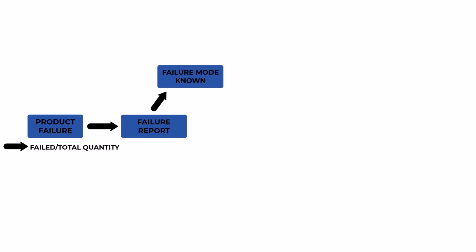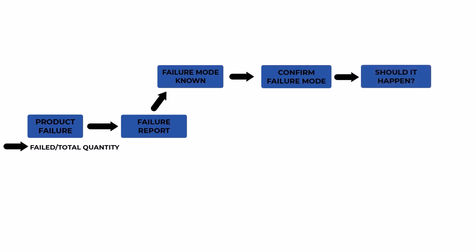If the failure is known, for example, I did A, and then failure happened, then we can move forward by replicating the steps that led to the failure to prove that was the case and that there were no other conditions contributing to this failure. Once we prove that was the reason for the failure, we can proceed with analyzing if this failure should or should not have happened. That means reviewing our user cases, calculation reports, intended environment, product specifications, etc.